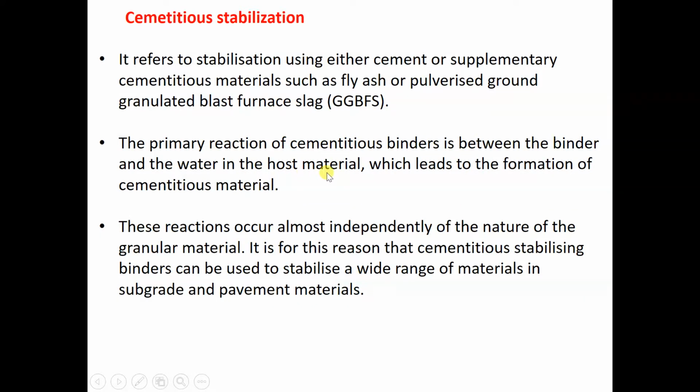You could apply it in the pavement, either in the base course or the sub-base, and you could put it in the subgrade as well. But there must be water for the reaction to happen between the cementitious material and the water, so that they can form the binder for the host material.